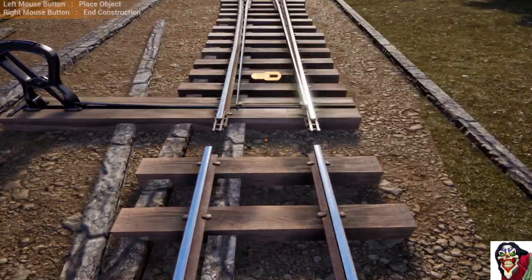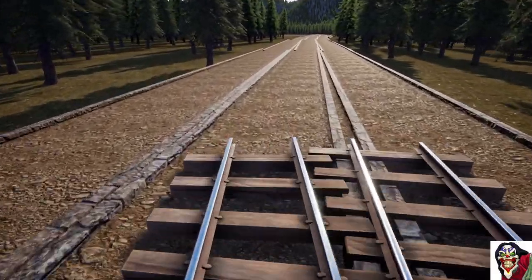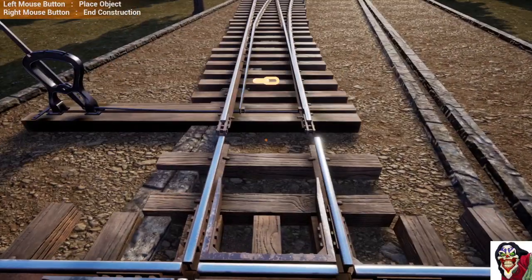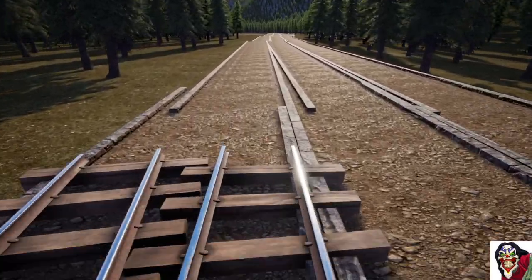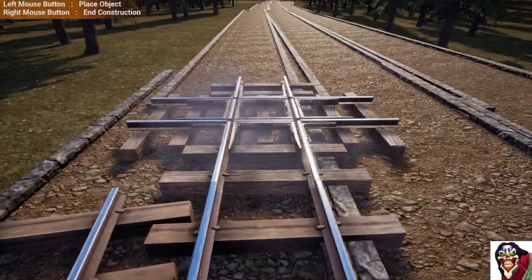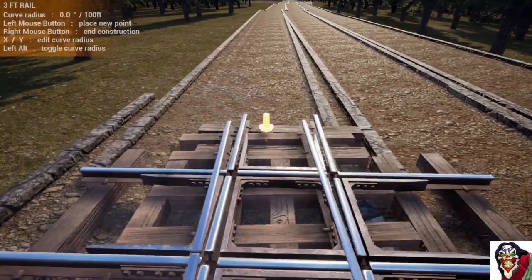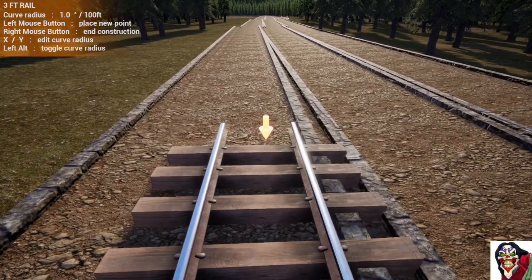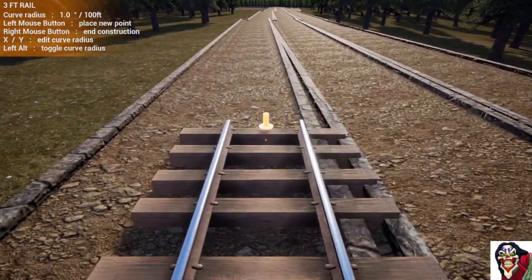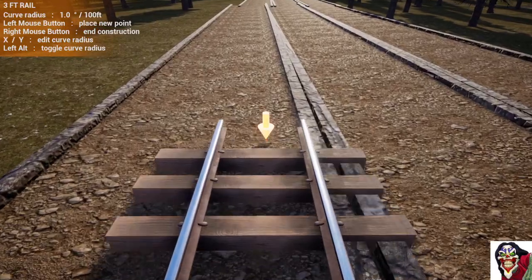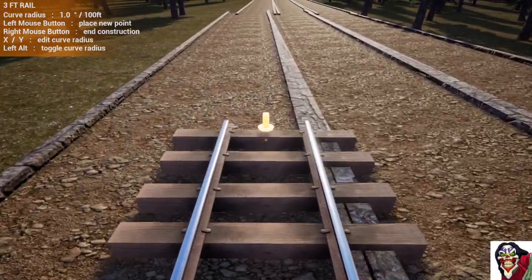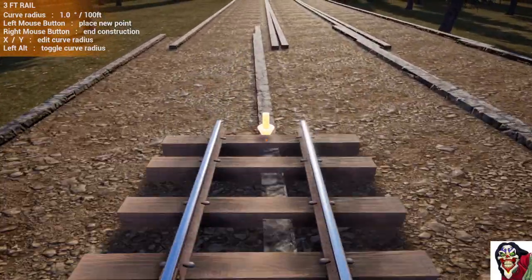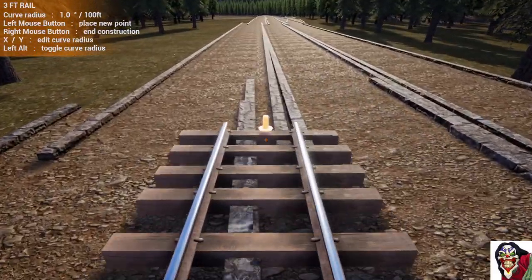Now we'll put in the switch to the passing lane, and we want to have a cross track spacing on the passing lane, so we need a cross track in the middle. And this one here just gives our position to come back again so that we're parallel. Put a cross track on the end, and now we'll put the passing lane in first, because what I'm going to do with the passing lane is put a very gentle curve in it to the right. And what this will show is the method of putting in parallel tracks around a curve. Of course, the hardest way to do it is parallel tracks around a very shallow curve. That's why I'm using just a 1 degree curve.